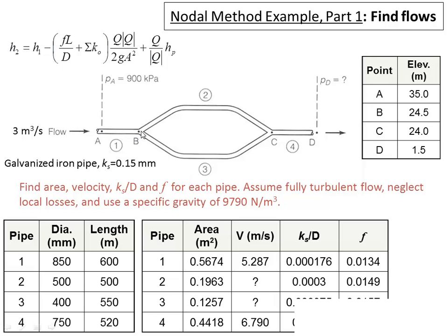We can find the energy at B by applying this formula. We would just apply the energy equation to find how much losses are there between A and B. We've got some new elevation we're going to have to take into consideration. We know that through pipe 1 there's a certain length. It's got a certain area, velocity, relative roughness, F value.